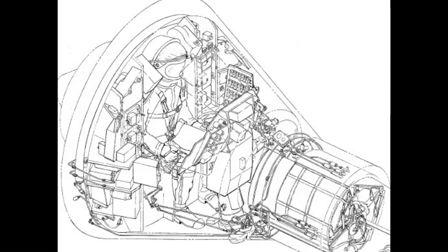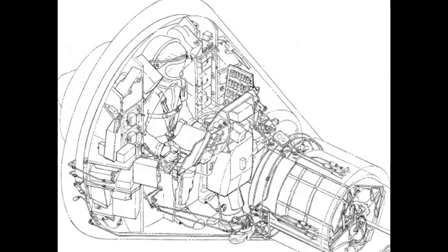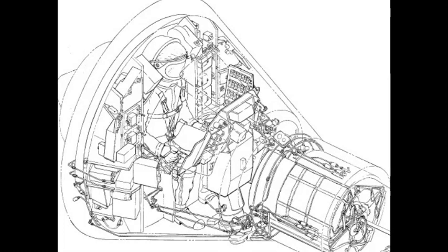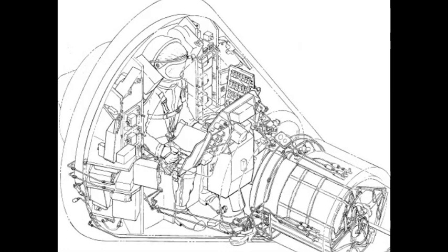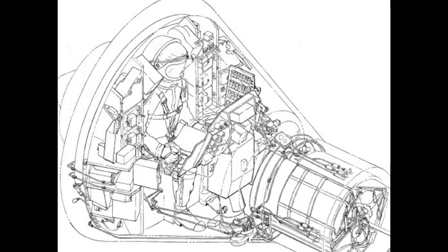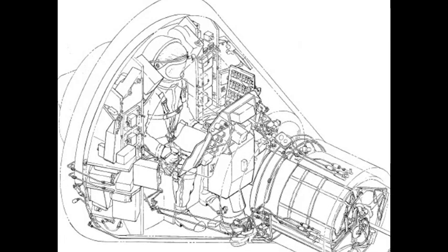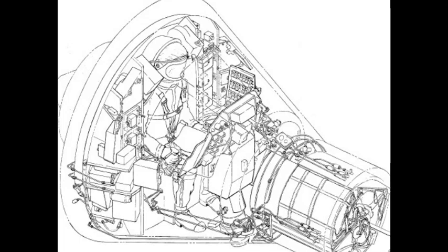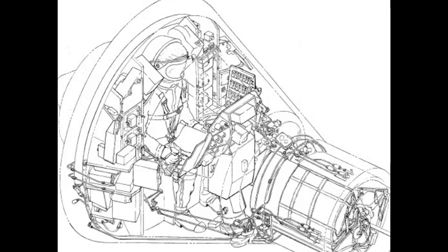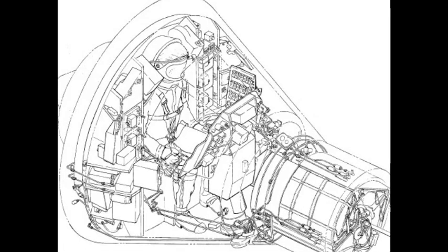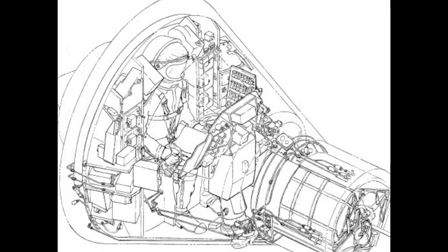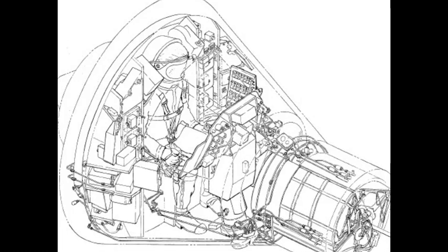2.7. An entrance hatch, Figure 2.2, is located on the right side of the afterbody conical section as viewed from the capsule crew member station. An explosive charge, molded in the hatch sill, is provided to enable astronauts' rapid egress from the capsule in the event the capsule lands on land. Entrance hatch construction, similar to the conical section construction, consists of an inner and outer beaded skin, seam welded together, and reinforced with hat stringers.